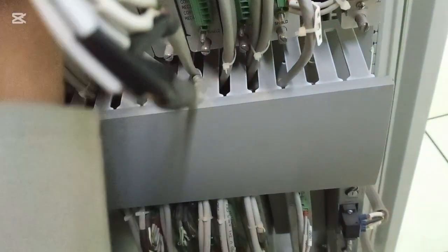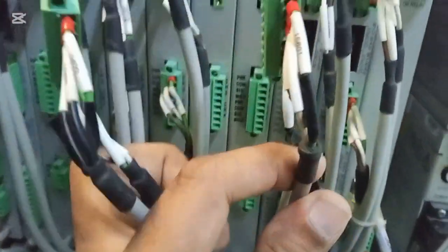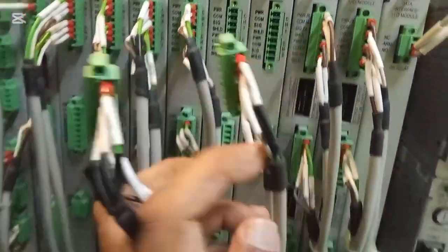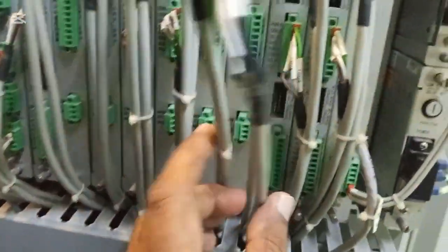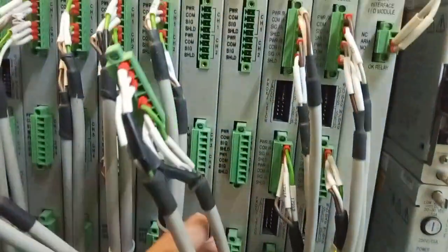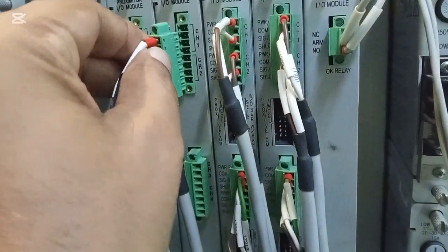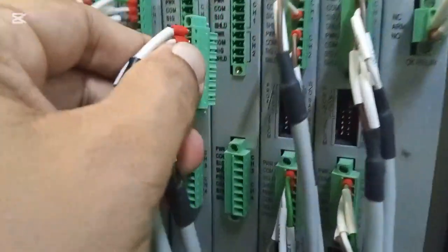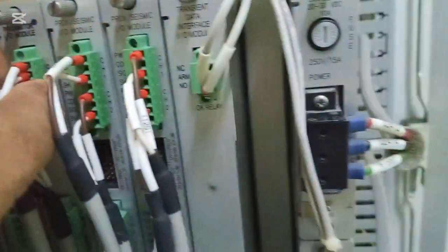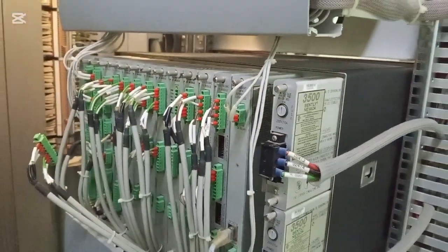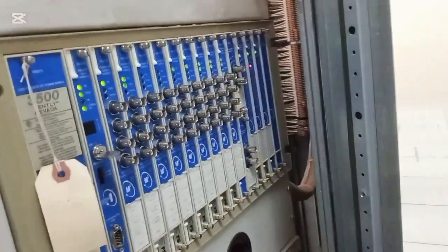Also we found different sensors, that means the sensor for seismic vibration and also for radial vibration. For seismic vibration, the sensor side voltage was 6 volt DC and for the radial side a 24 volt DC supply. Different cards are used here, and we identified a different card for each sensor, that is the proximity sensor and also the vibration sensor.